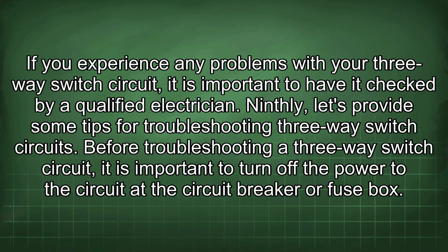Ninthly, let's provide some tips for troubleshooting three-way switch circuits. Before troubleshooting a three-way switch circuit, it is important to turn off the power to the circuit at the circuit breaker or fuse box.